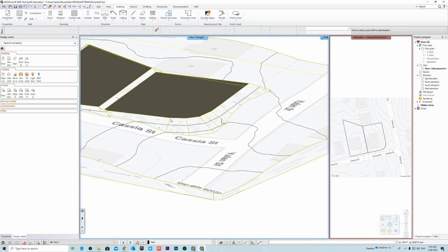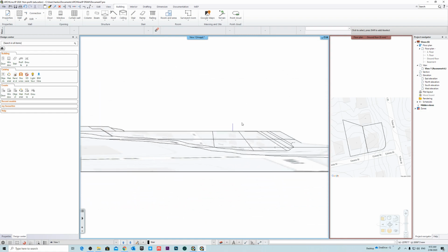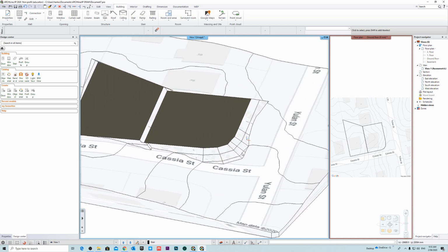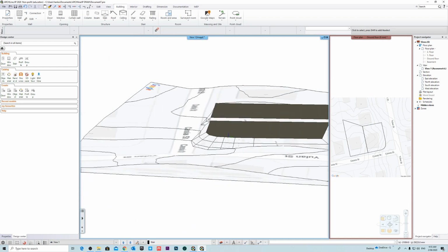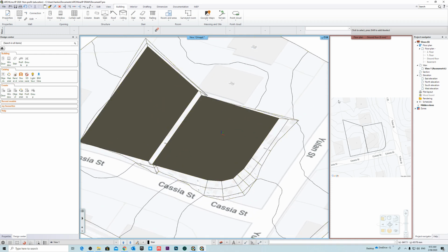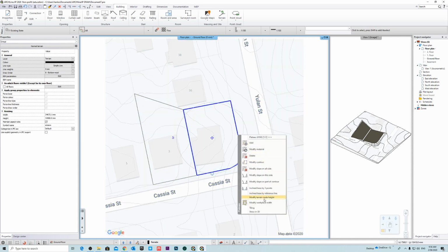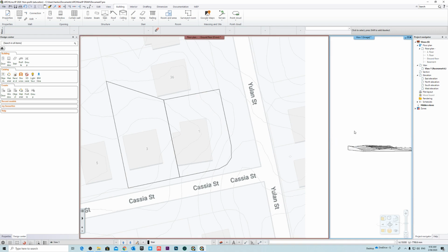Right now, maybe this one is still a little bit high. No, it could either be that this is actually built on a slope. So you could always change it, depending on where your building is sitting. All right, but for now, we'll just sort of go with that. We'll just make it a little bit lower. We'll go modify terrain node height, and we'll take it back to 33. Okay, and that should be okay.